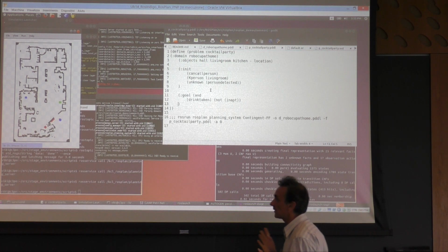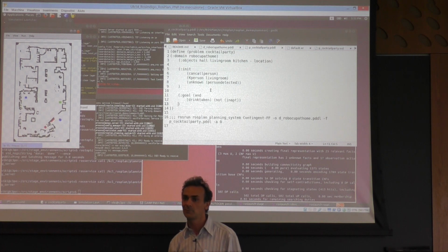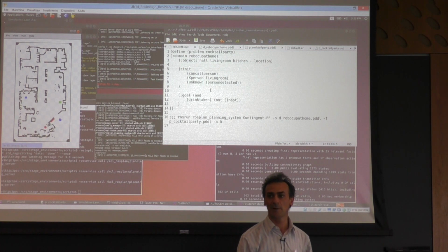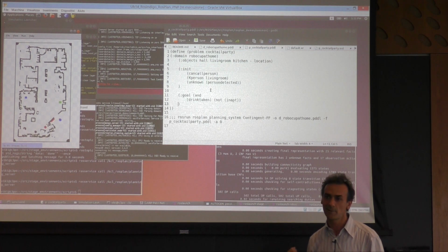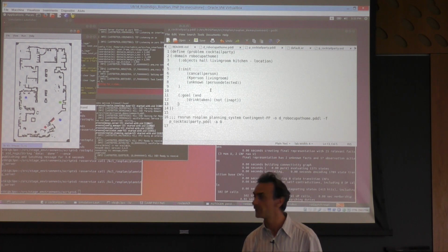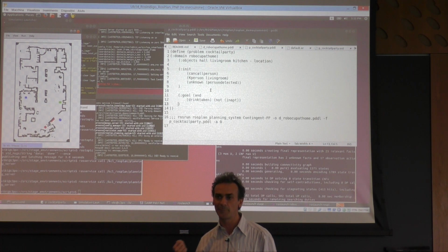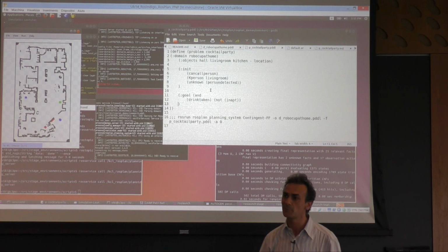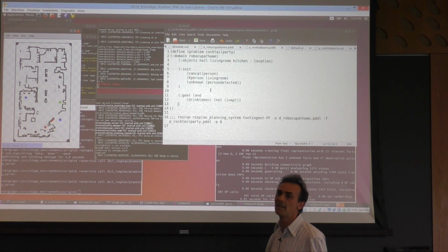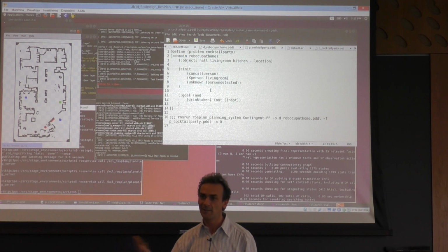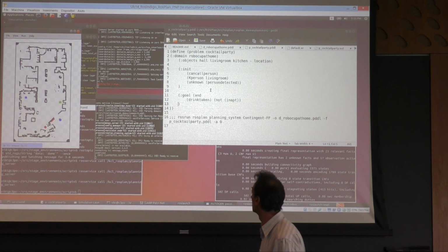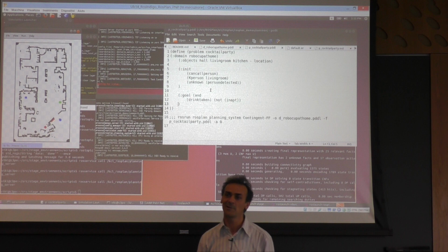So in that case, the rules allow two behaviors. If the robot is able to detect the person, then the robot should approach the person and say something. Otherwise, the robot can call the person. So if the robot is not able to detect the person, it can say, "Hey person, please come here." And so the person will approach the robot. So depending on this situation, there will be this branch in the conditional plan.